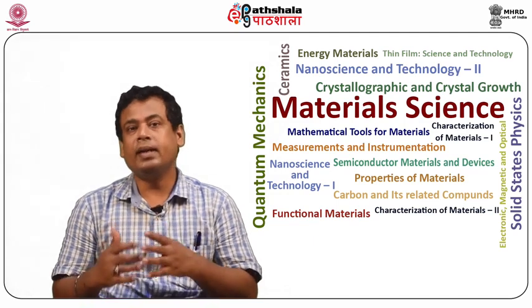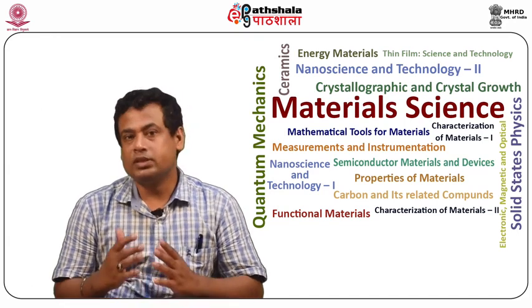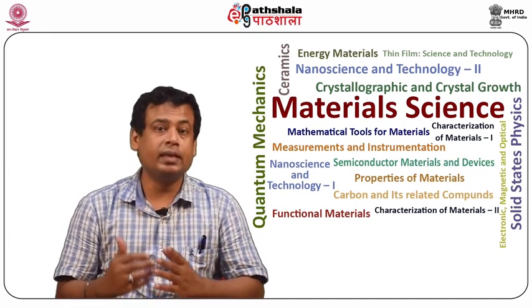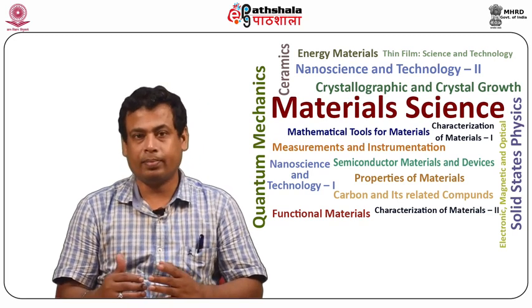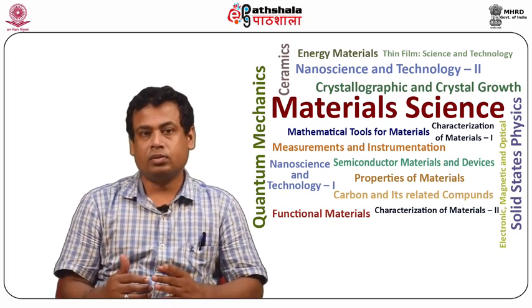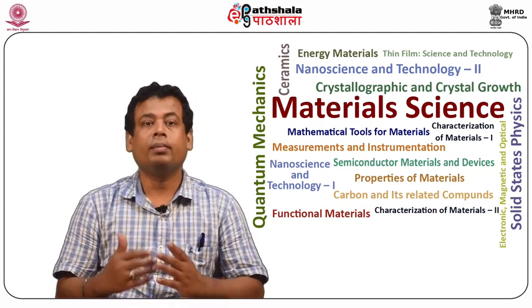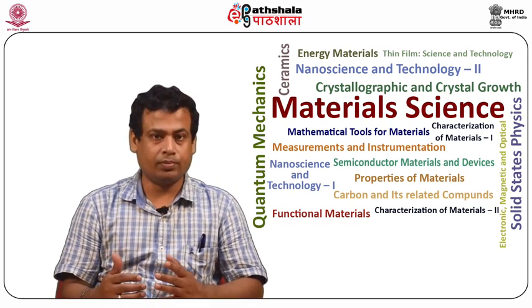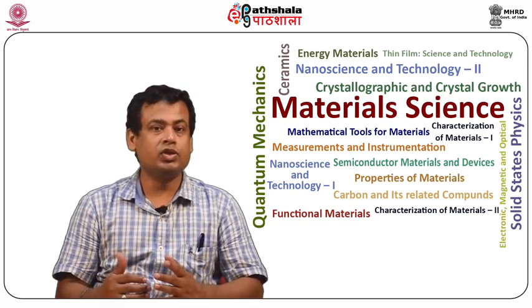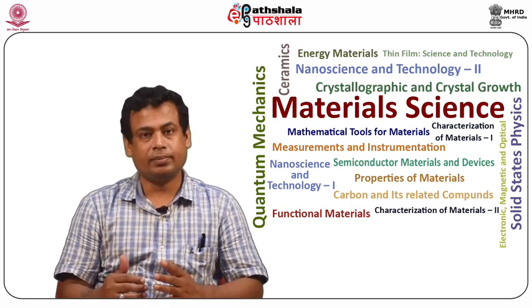The most widely used substrate is silicon, which is semiconducting, with a thin insulating layer of silicon dioxide on top. Other substrates that can be used are glass plates coated with metal chrome, widely used in mask production, in which the metal layer should be grounded before drawing.